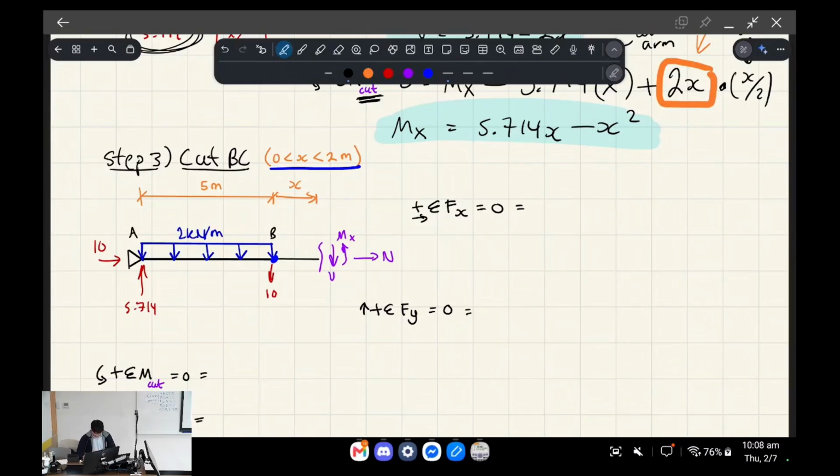So we're going to derive the axial force first, and what you'll find is that N will be pointing to the right, so we're going to add it, and then we're also going to add 10. So just like before, the axial compression is going to be negative 10, which shouldn't be too surprising considering what we're saying is that from A to B, we're going to have 10 kilonewtons of compression, but from B to C, that 10 kilonewtons of compression is just going to continue, right? So it's going to carry on.